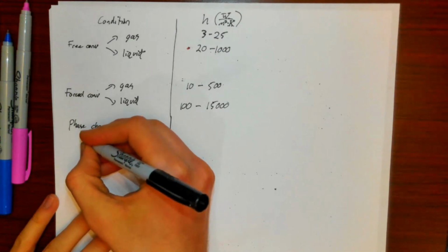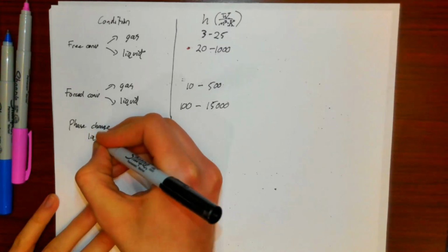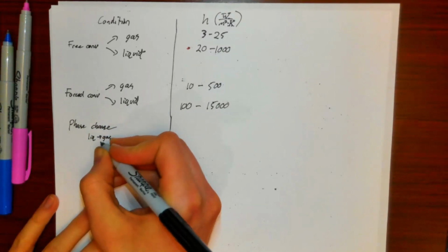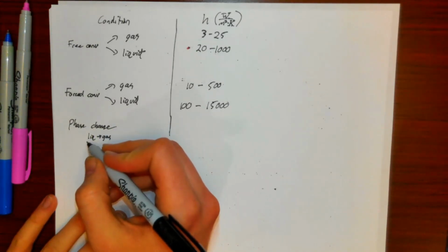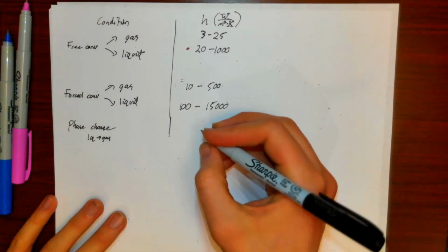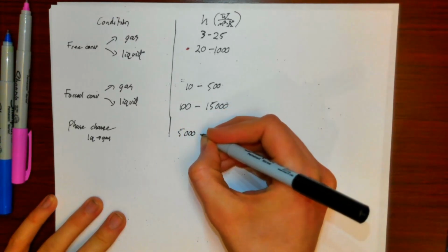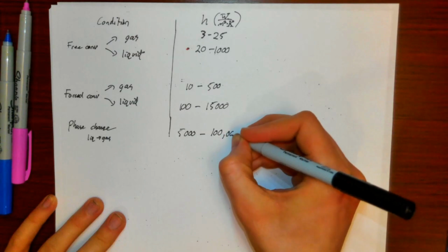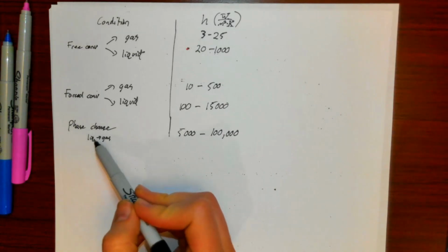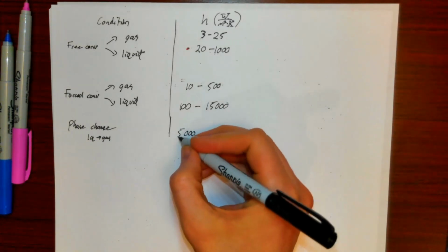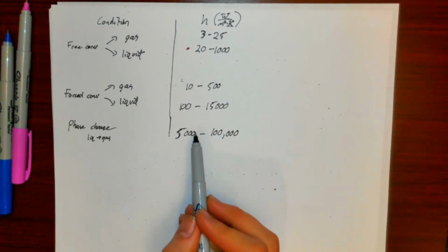But this phase change, for example, where the fluid in contact with the solid goes from a liquid to a gas, actually gobbles up a ton of energy in the process. So convection due to a phase change, where we go from a liquid to a gas, can actually be even better than some of these, something maybe in the range of 5,000 all the way to 100,000 watts per meter squared Kelvin. So what's the key thing? If you want to cool something down quickly, basically pour water on it where the water boils away. And you can get very, very high heat transfer coefficients from that.